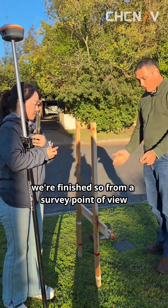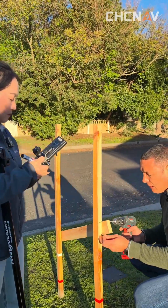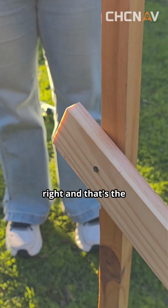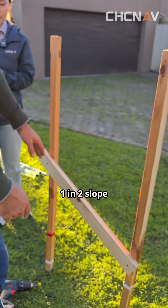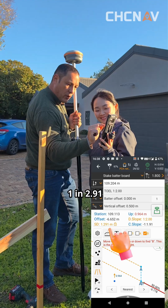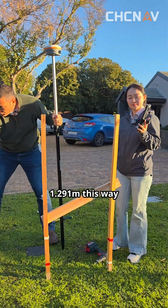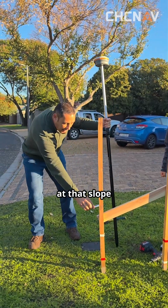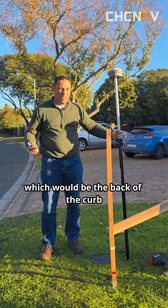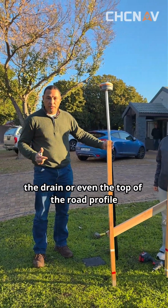So from a survey point of view, I am pretty much finished, and this is how quick it is with LandStar to put in a batter board. Right, and that's a 1 in 2 slope. There's a slope distance, 1 in 2.91. Yeah. So from this point here, 1.291 meters this way, at that slope, is the intersection of our next design feature, which would be the back of the curb or the top of the V-drain or even the top of the road profile.